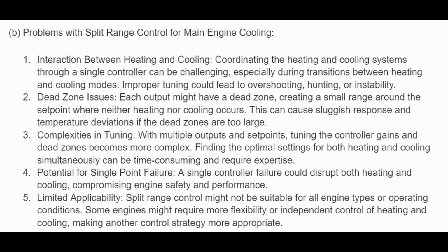B. Problems with split range control for main engine cooling. 1. Interaction between heating and cooling. Coordinating the heating and cooling systems through a single controller can be challenging, especially during transitions between heating and cooling modes. Improper tuning could lead to overshooting, hunting, or instability.